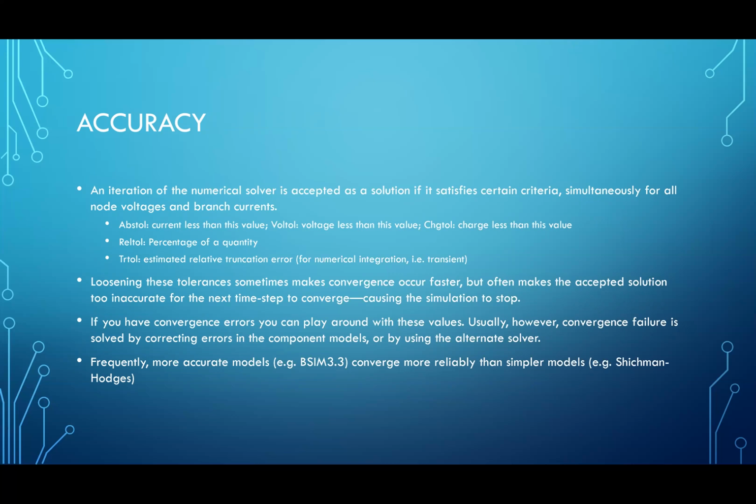Well, so again, it runs on a numerical solver, an iterative solver, right? And these iterations for the iterative solver, they converge. With each iteration, it gets closer and closer to the actual answer, but it never actually reaches the true solution. It just converges toward it. In the limit, as iterations approach infinity, it converges to the true answer. But you're not going to spend infinite time performing infinite iterations. So at what point does an iteration become accepted as the answer?